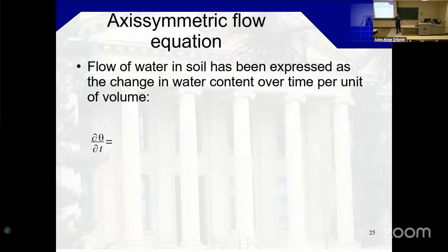The loading, we're going to see a way of adding loading that could work for any kind of loading, but because it's an axis symmetric problem, it will have to be kind of circular in that sense. But I want to show a little trick with the basic definition of Boussinesq that can be used for any kind and shape of loading pattern if you have the coordinates of your area.